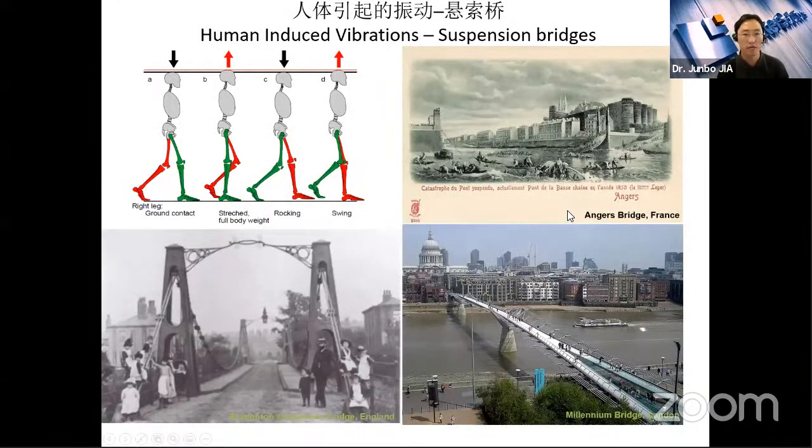And it's not only nuclear power plants; other types of structures are also sensitive to dynamic loading. Even human beings or animals can cause resonance problems. For example, when a person is walking on a bridge, or on the floor of a building, the walking is like a series of vertical forces acting on the floor. If the frequency of the walking is close to the eigenfrequency of the floor, it can cause a problem of resonance and even the collapse of the entire structure.